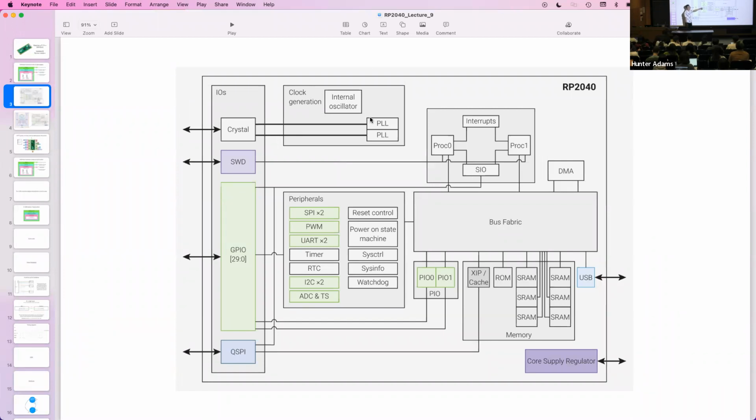I'll just remind you that this internal microsecond timer is 64 bits. The 32 least significant bits live in one register, and the 32 most significant bits live in another register. So the amount of time it takes for that full 64-bit timer to overflow is like 500,000 years. But the amount of time that it takes for the lower 32 bits to overflow is like 72 minutes or so. So if you're trying to schedule code for execution farther out than about an hour, the real-time clock is a reasonable alternative to the internal microsecond timer.